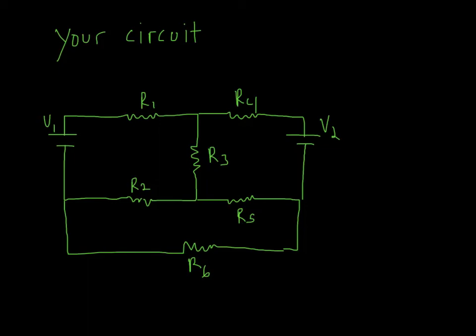But something I just want you to take note of is you're going to have two voltage supplies, two power supplies. In Multisim software, they want you to put a ground on the circuit. And so where do you put a ground? You could put a ground on this one and this one, or you could put a ground just on this one, or just on this one. And those are actually two very different cases. All right. What would happen if you put a ground on this one and this one? Pause it maybe for a little bit.